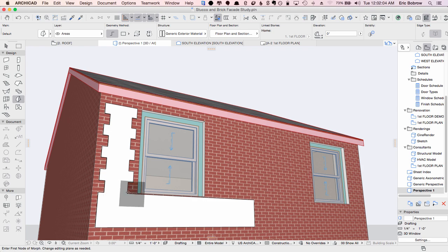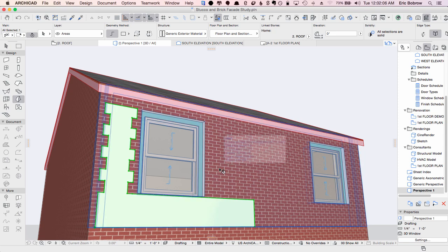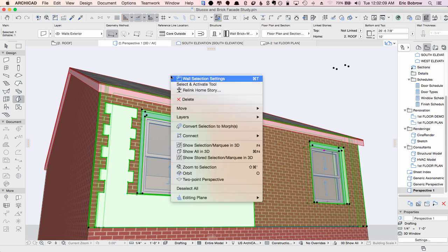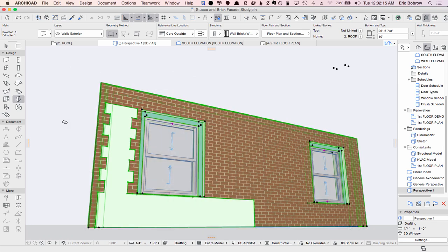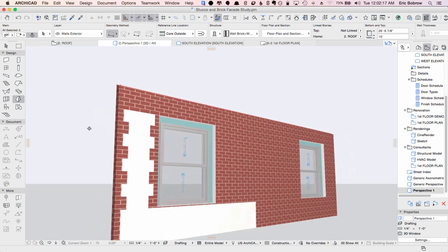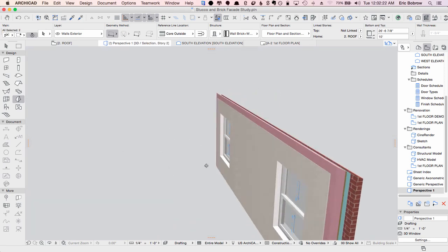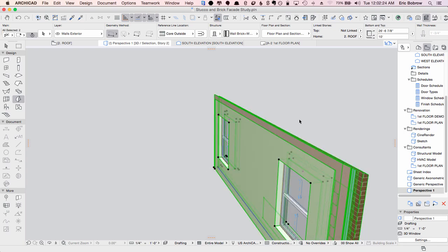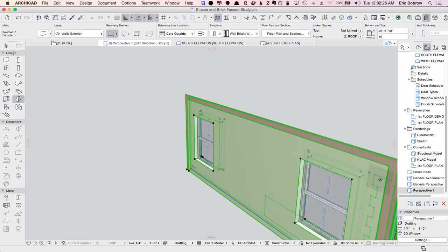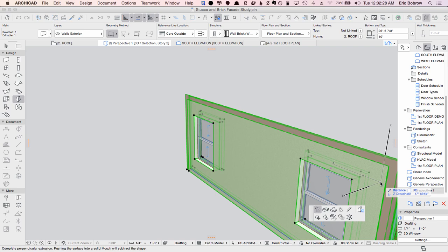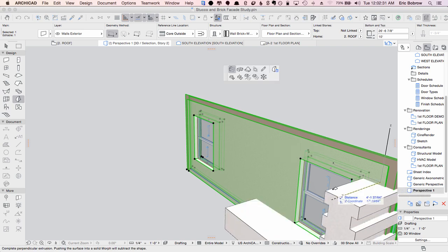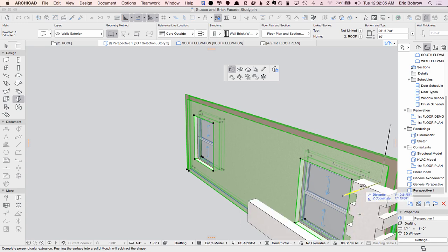So here's how we do it. I'll select the morph and this wall and use an option not too many people realize is available, where you say I only want to show what's selected in 3D. So in 3D I can switch and say temporarily show only part of the model. Now having done that, I can go to the back here and take this face here. So even though this was buried in the wall, I can still hover over that face and pull it.